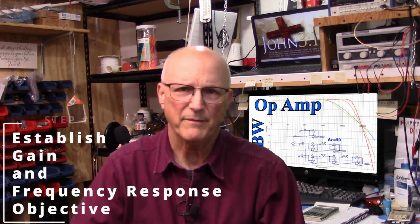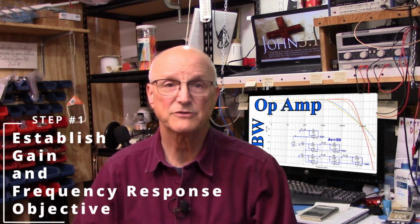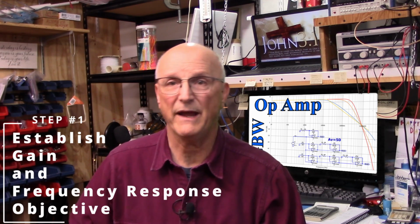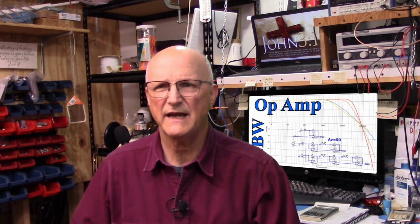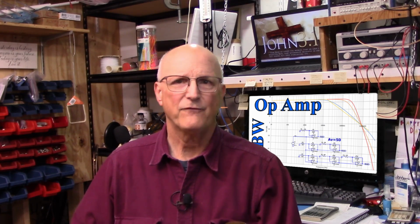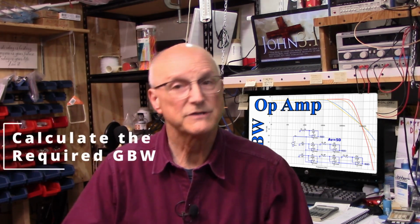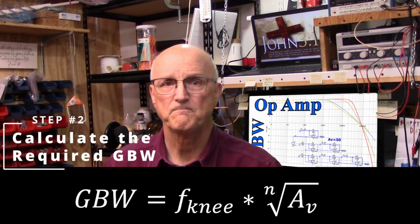So how do we choose an op-amp with this in mind? Well, the first step is to establish what our overall gain and frequency response requirements are. This will define the minimum gain bandwidth product that we're going to be looking for. We remember that this number determines where our amplifier's gain will be 1. If we are expecting gain that is greater than 1, then this number has to be higher than our desired cutoff frequency.